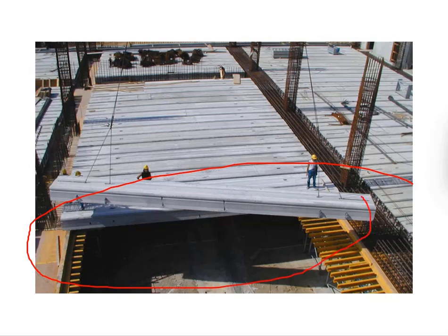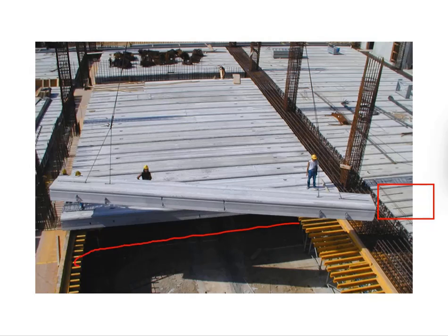Taking this as an example, you see the slab on the other side has already been installed, whereas the slab on this side is still in progress. Imagine the loads taken by this stretch of the member. You have load on one side, but you don't have the load on the other side yet. This leads to torsional force. Of course, in this case, you have propping to support.